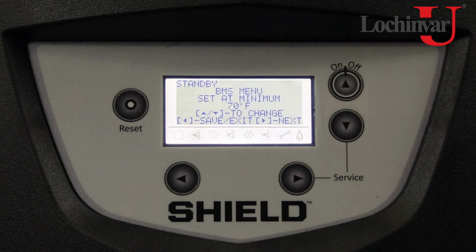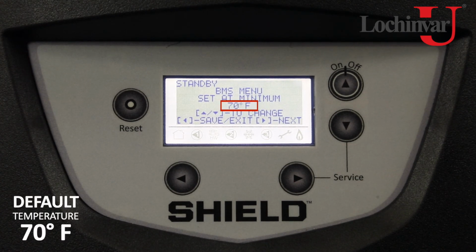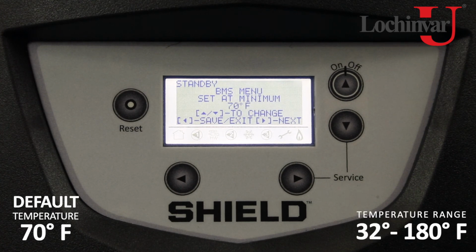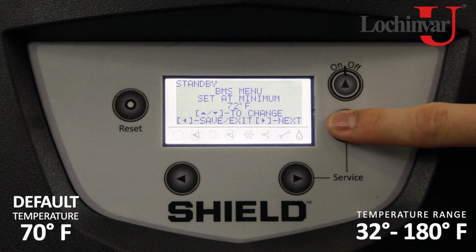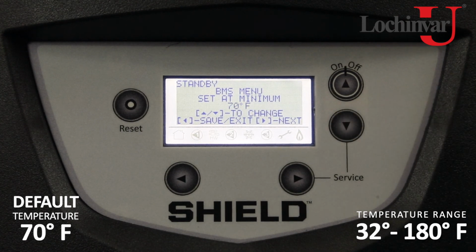The ninth parameter visible is SETPOINT at minimum. When the BMS type parameter is set to SETPOINT, this parameter will determine the set point of the unit when the 0 to 10 volt DC signal is at or below the setting of the voltage at minimum parameter. The default temperature is 70 degrees Fahrenheit. The temperature range for this parameter is 32 to 180 degrees Fahrenheit.